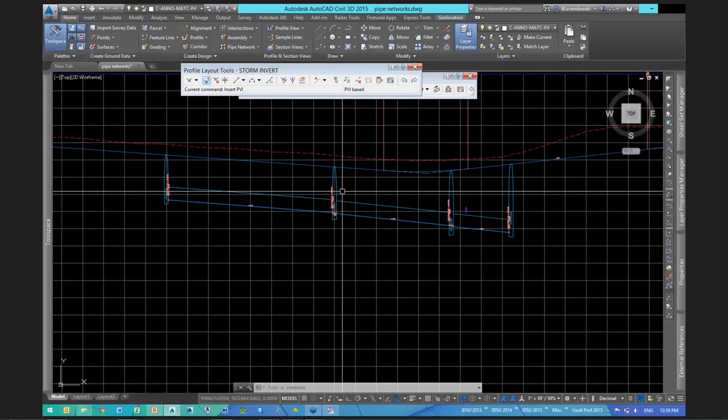If it was just rims you were trying to bring down, you could create a different surface, paste in the original surface into it, and do a raise/lower on that surface. Then you could change the reference surface on all those structures, and that would push the rims down. If you reapplied rules to pipes and such, it would push those down, but it wouldn't be an even thing. So unfortunately, there's no easy button there that I know of.